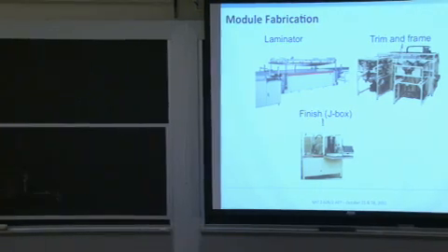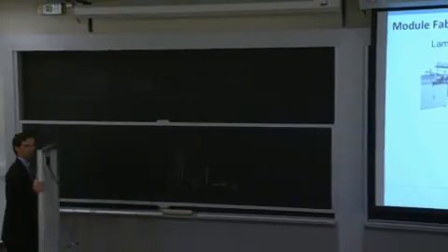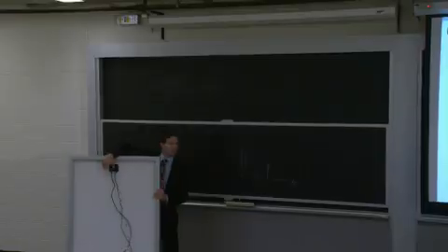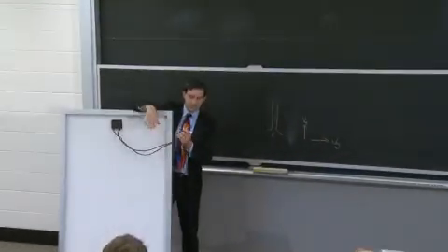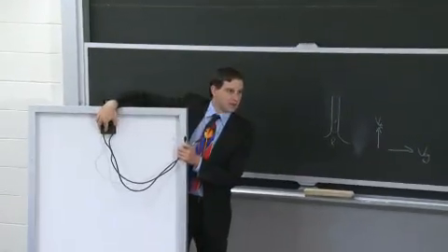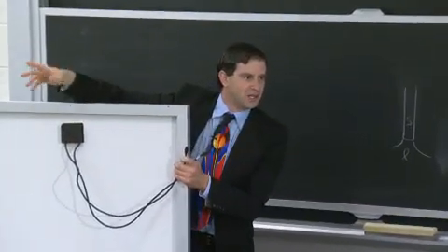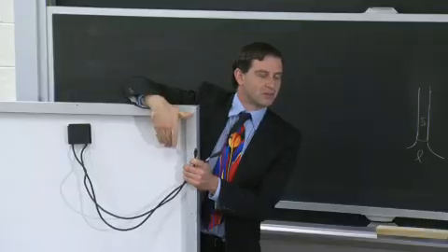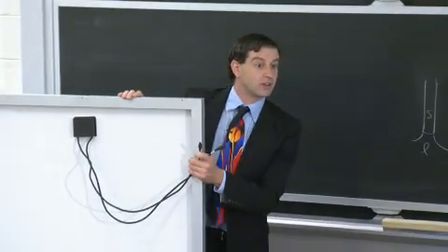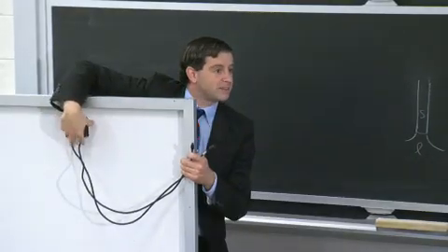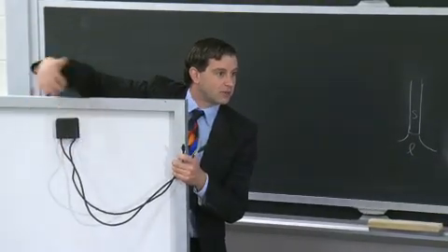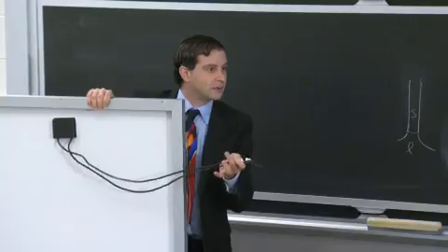And the junction box, what it does is it collects the power outputs from each of the cells and very conveniently gives you 2 leads. Right? So there could be some power electronics inside of here that allows the current to flow around this module if this module is underperforming, if it's broken, or if it's shaded. There'll be a bypass diode inside of the junction box that allows the power to flow around the module and not get sunk into it.